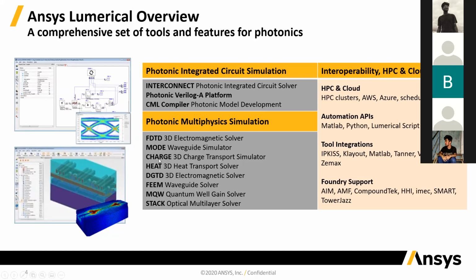The charge solver is our electrical transport solver. This is also a 3D solver. It uses drift diffusion based simulation technology, which is standard in the industry. And this allows you to, for example, simulate the transport of electrons and holes inside your semiconductor devices, like solar cells. The heat solver is next, and this is our heat transport solver, also a 3D solver.